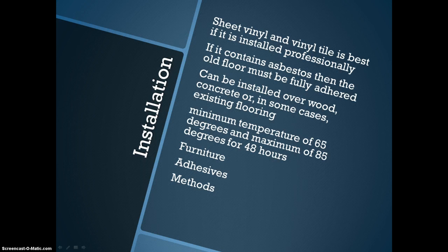The floating, which is the glueless installation method, is just vinyl sheet flooring designed to lay on the floor with no adhesives, but it can use some tape at the edges and under seams to make sure that it is sealed down correctly. Fiberglass is usually used as a backing, making it a little more stiff. The self-adhesive installation method is the peel and stick tiles. The adhesive is already applied to the tile, so all that you need to do to position and apply the tile is to just peel it off.